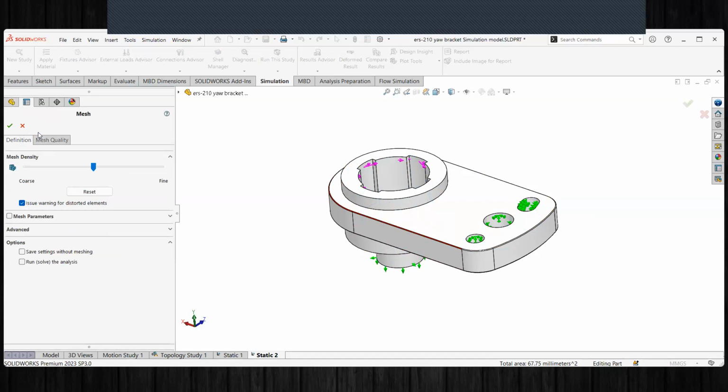If you're starting off, this is just part of it, right? You can really geek out and deep dive into theory of meshing and capabilities and things. But the nice thing is that if you're new to simulation, it's pretty forgivable. We use tetrahedral elements, which are really easy to mesh geometry in general. There's many different types of element types out in engineering simulation, but we stick with a pretty forgivable and easy to work with element type for simulation in SolidWorks.